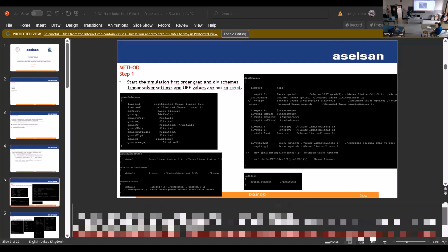We can see that at the near side of the body and the leading edge, there is a separation bubble, and we can also emphasize this. As a conclusion, most CP distributions mostly overlap with the experimental studies, and it shows that the high mesh sensitivity of OpenFOAM can be handled with the proper steps, and tetrahedral mesh can be used for a very wide range of problems with different complexities.